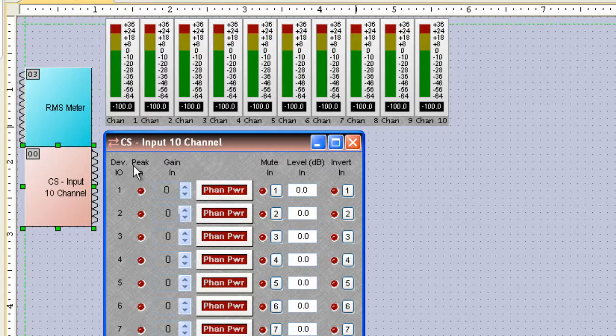The most important part, once again, is to raise our gain up to where our meters are reading between 0 and +8. If we peak, we'll see a little peak light, and it'll come on about 6 decibels before the actual peak, so we can back it off just a little bit. If we're at 0 to +8, it allows us room for the really loud talker, and it allows us room for the really soft talker, and we're still real close to the 0 dB, and everything else downstream will work much better.